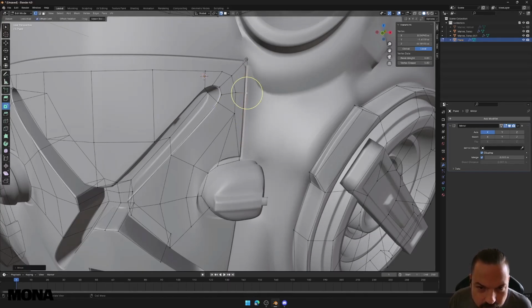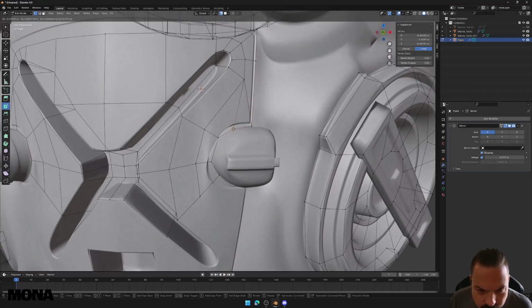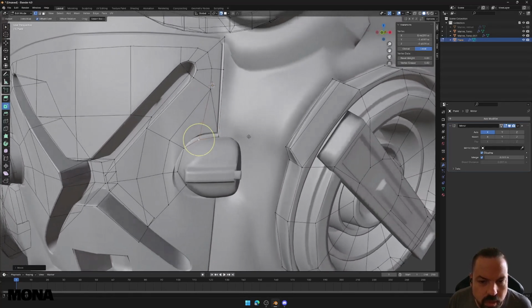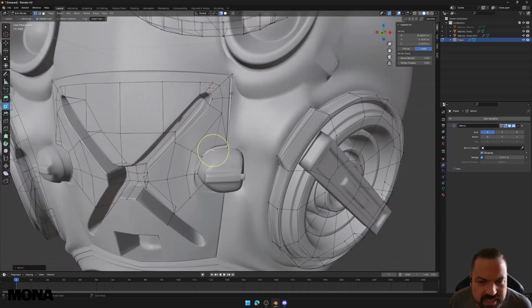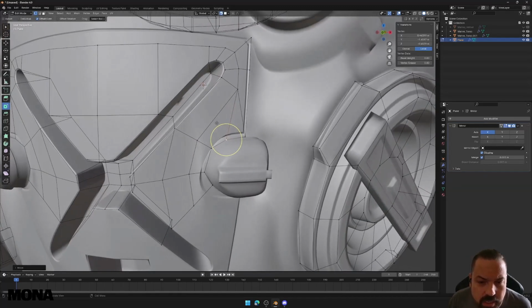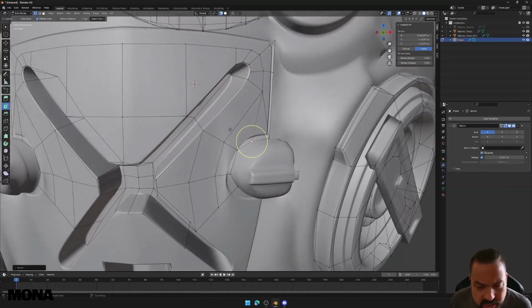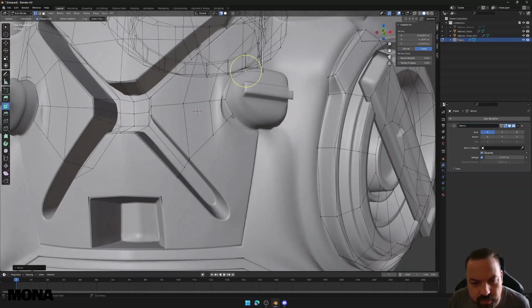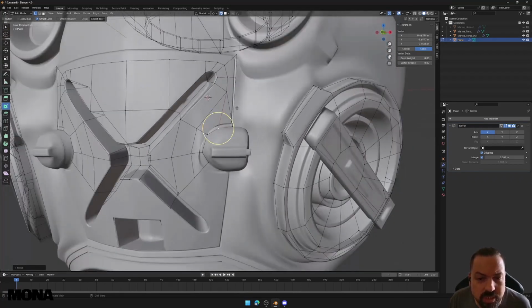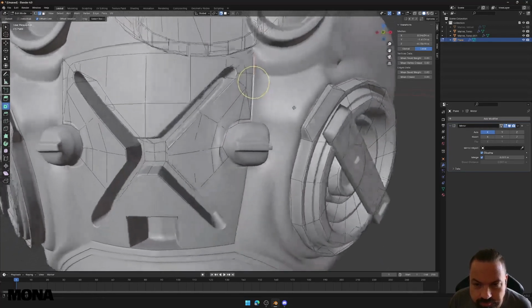G, not F. Again, let the normal map do its job. So that triangle, for example, is fine. This is never going to animate. And once again, the occasional triangle, if it saves the polygons, is fine. That said, I could put a line up there into there. So that's another approach. It's always a balance between figuring out which things require more polygons and which ones don't. I'm going to go with don't for this one.